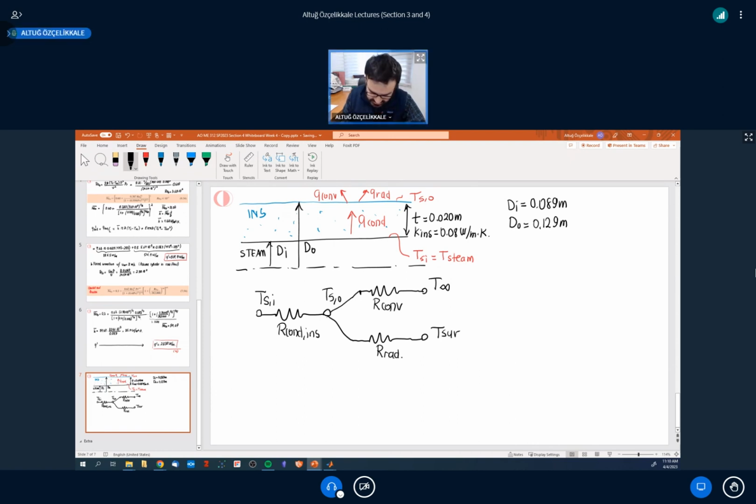We can represent the Stefan-Boltzmann law in a way that we can come up with a ratio of heat transfer rate and a temperature difference, and the result of that ratio is essentially the radiation thermal resistance. So the conduction heat transfer, let's call this Q1, is going to split into two, associated with convection and radiation here.